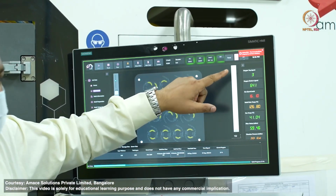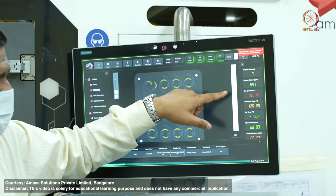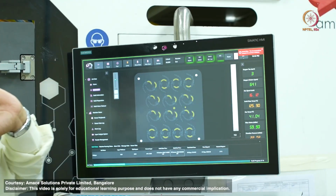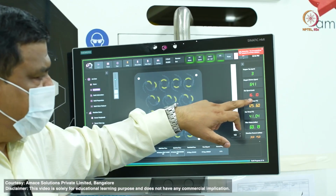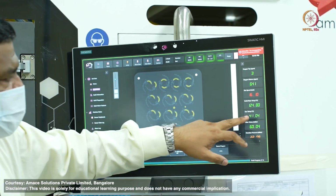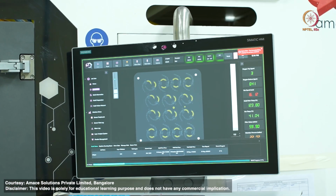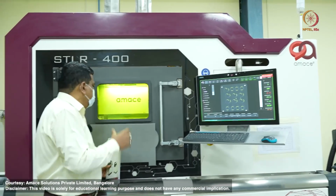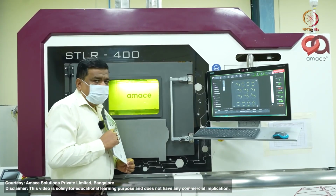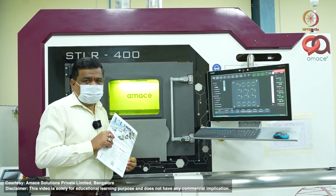And if you look, this is a precipitation hardened steel. The oxygen content here is around 630 ppm. The gas speed, that is the inert gas flow rate, is 16 meter per second, and the build plate temperature is currently 127 degrees Celsius.